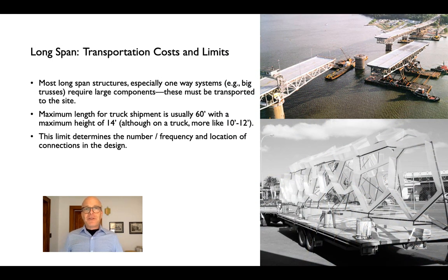We don't often think about this, but in the back of your mind, you may realize that we actually have to get all of these pieces to the job site. If we're designing a bridge, that might be very easy. We might be able to get very, very large pieces into place on barges. Architects usually are working with landlocked sites, and so everything that we put into our building has to show up basically on a truck. And there are limits to the size of things that we can put on highways in particular. So 60 feet is a standard maximum length and a maximum height of 14 feet. Although if we're shipping by truck, usually that's only going to be more like 10 or 12 feet.